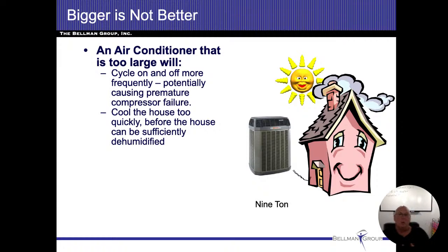The ultimate goal of an air conditioning system, when it's properly sized, is that it should pretty much run 24 hours a day on those temperatures of around 100 to 110 degrees in our area. And as it's running, it's constantly removing the heat that's coming in, and constantly removing the humidity coming into the house. It's giving you comfortable, cool, and dry air. Now, that doesn't mean that it won't shut off here and there, but for the most part, it's going to turn on and stay on.